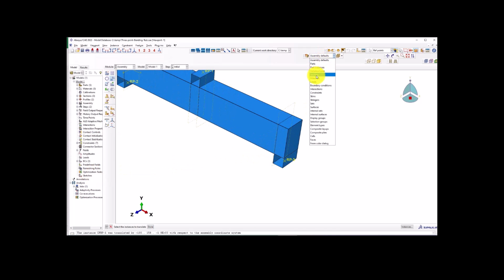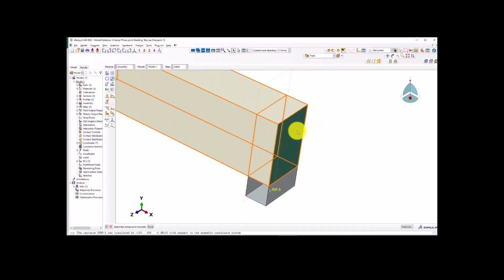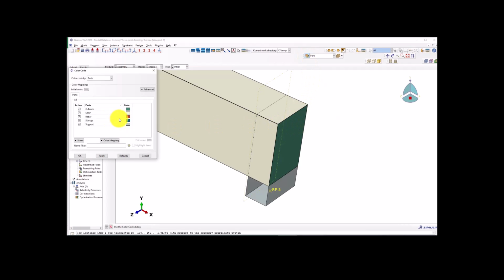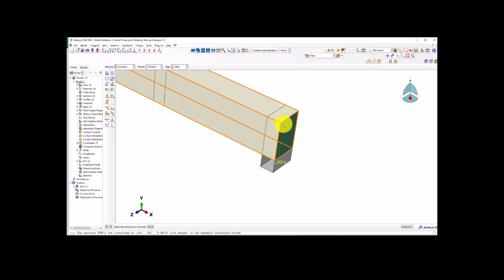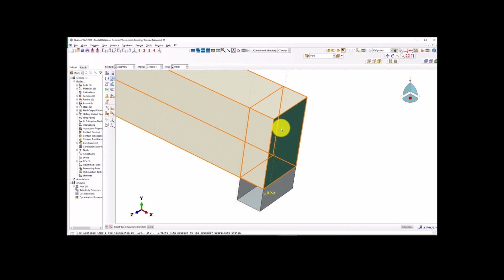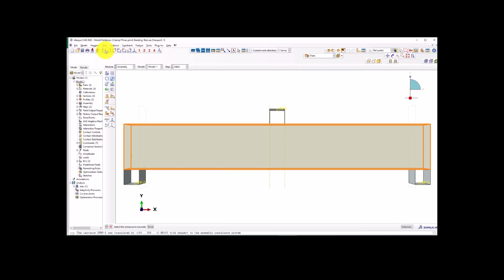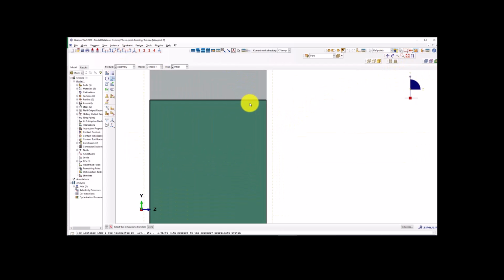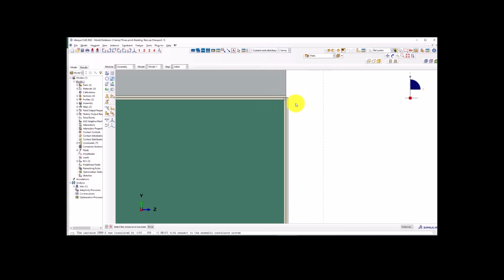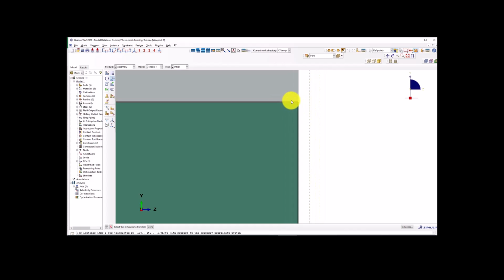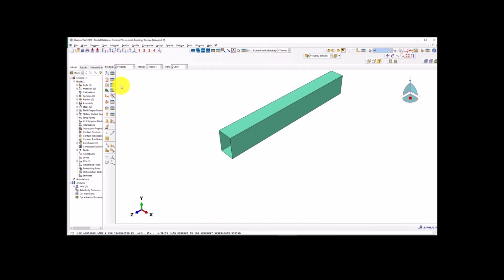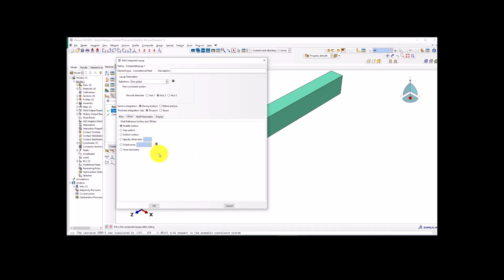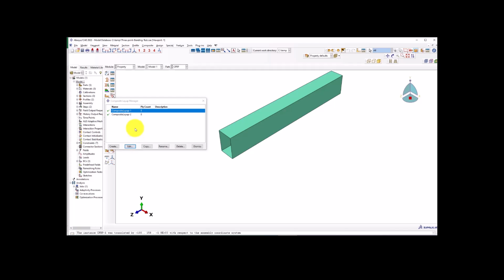So I want to see, let me go to section instead of section part, and we can see one is the red one in the part, the green one is concrete, and the white one is CFRP. So let's see here, and the problem is that the CFRP is taking center to center, so we want that to be outside of the concrete. For this purpose, in the first one, here is called offset. So we want to select bottom. Let's see how it works.